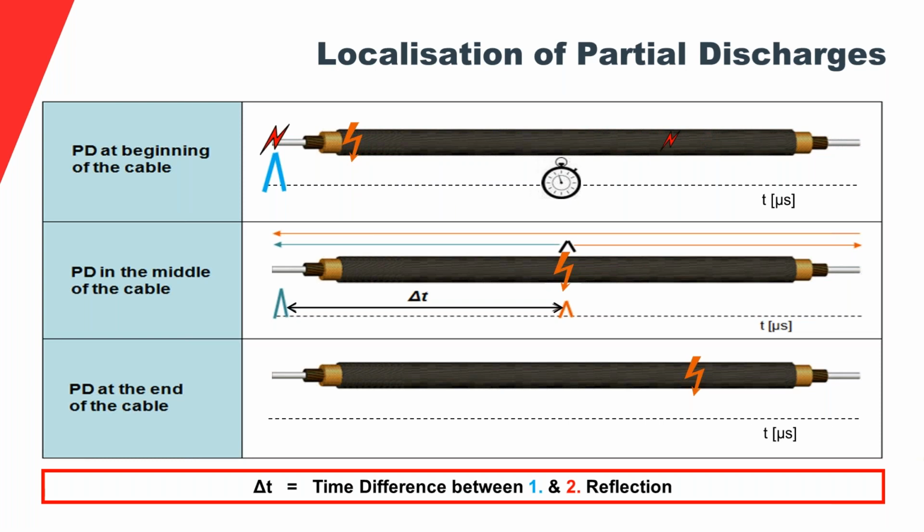Reflection at the end. Tick-tock, tick-tock, tick-tock. Arrival at the detector, and you have your second reflection. Now, as you can see, in this animation, it was attempted to show also what happens to these pulses, which is very important for the software algorithm that discriminates the pulses. Cables are capacitive assets with a strong low frequency filter behavior.